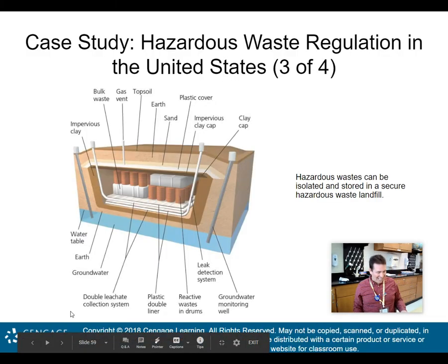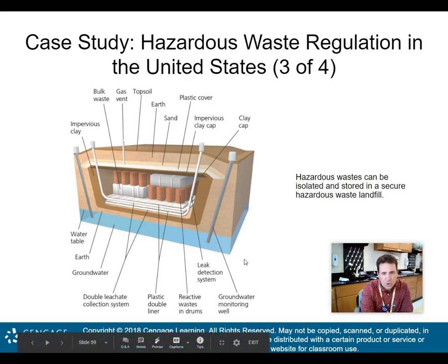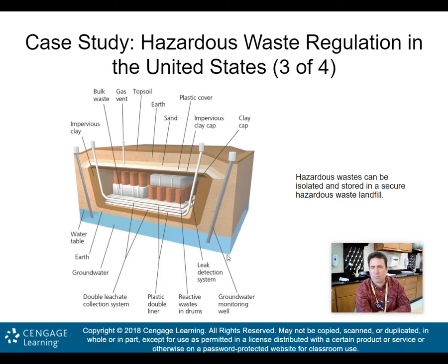Again, hazardous waste can be isolated and stored in a secure hazardous waste landfill. Again, this is not happening in the Ringwood mines. That's why it has become a Superfund site. But what do we have here? Just take a look. Here's your water table, here's that impervious clay layer, here's your waste, here's your gas vent, topsoil, plastic cover. You have a leak detection system so that if you do get some leaks, we can deal with it quickly. You have a groundwater monitoring well, making sure that the minute it gets polluted, we know it. Ding, ding, ding, alarms go off, and we go in there and deal with it.